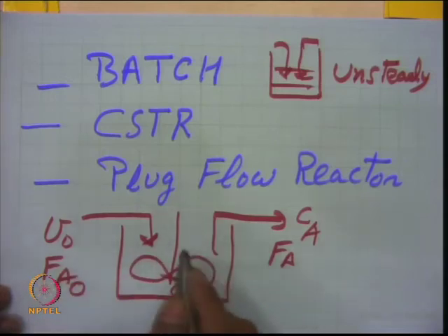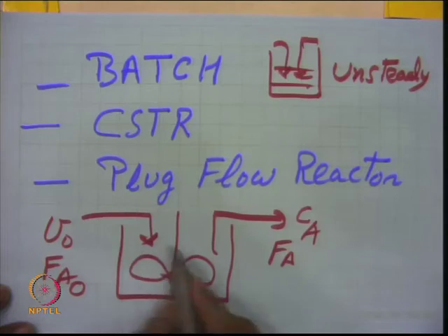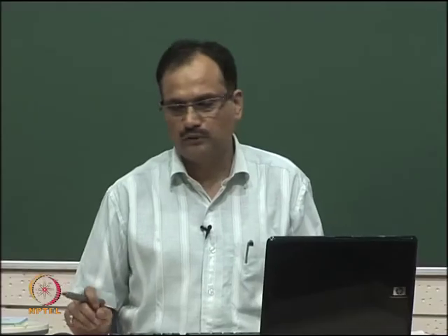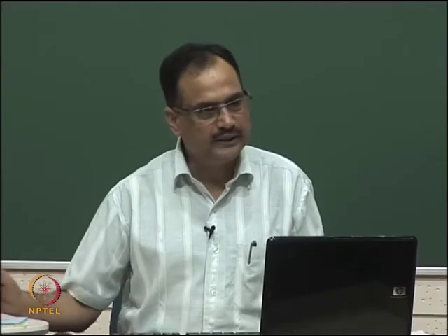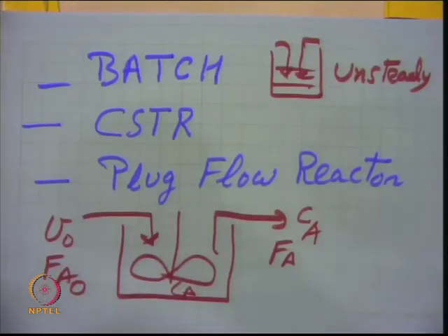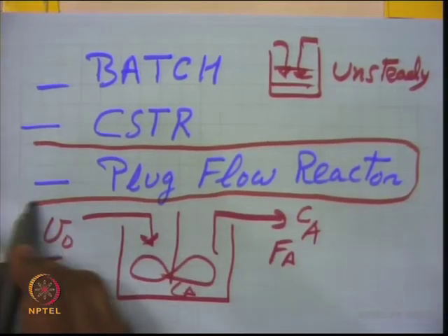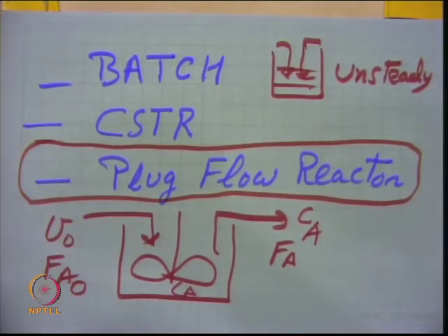So, it can be a kind of slurry reactor also when you have a solid particle, right. Mainly in homogeneous reactors, or where heat transfer is a problem, the CSTR type is used, because the mixing is good in this kind of reaction. So, where mixing is an issue or heat transfer is a problem in the feedstock or the reactant product, then the CSTR type of reactor can be used. But most of the time when you look at commercialization, large scale reactors are of this type, plug flow or fixed bed reactor.